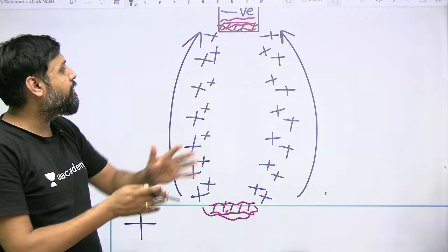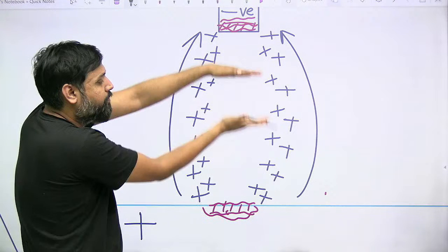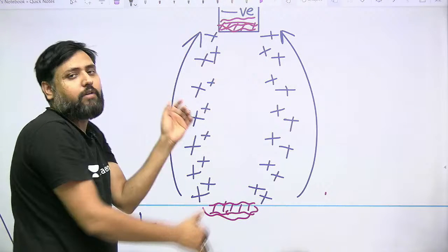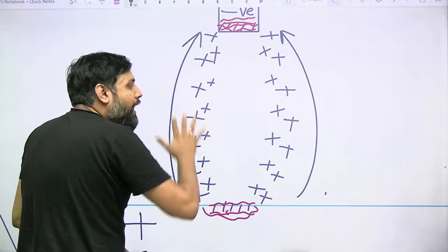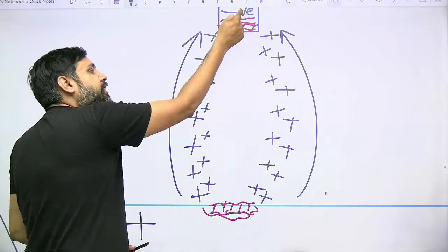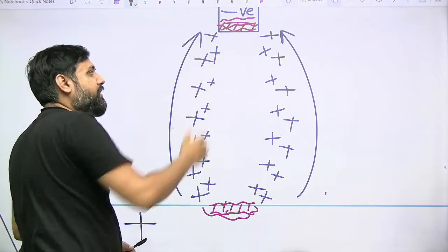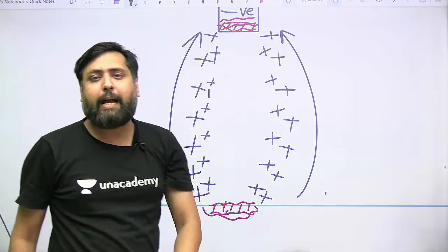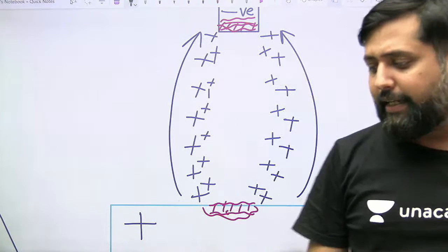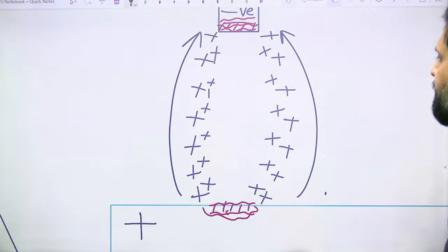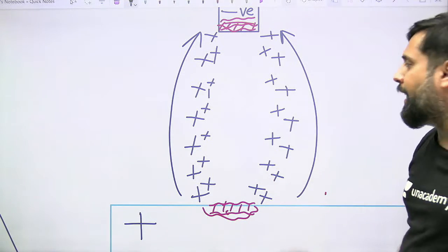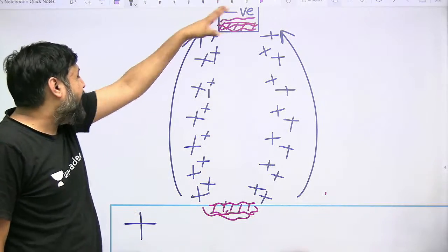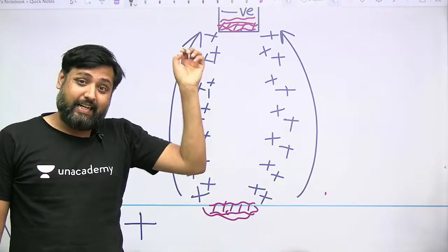what happens to the atmosphere between the electrode and the workpiece when these positive ions come out, emit out from the positive side and travel towards the negative side? The positive ions, which are emitting out and getting accelerated towards the negative end because they are attracted towards it, ionize the atmosphere in the gap of electrode and workpiece. Now my dear students, through this ionized medium electrons travel.